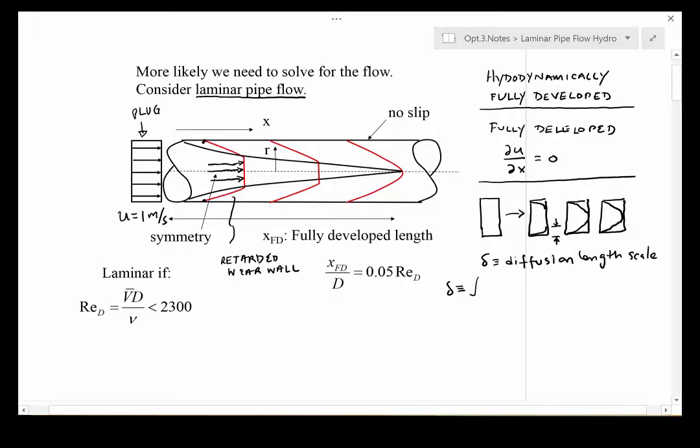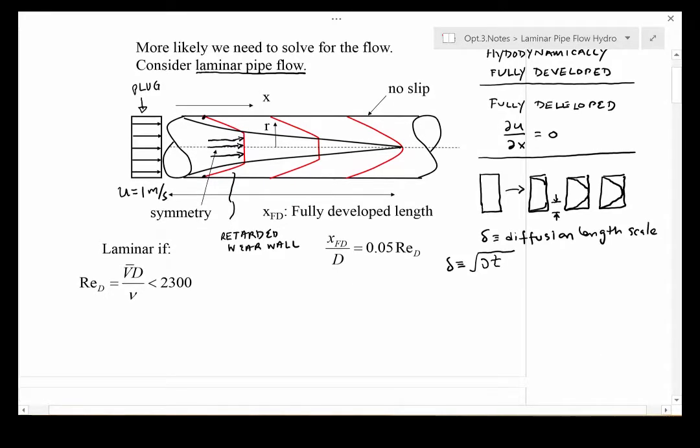There's a very similar relationship in the momentum problem that depends on the kinematic viscosity times the characteristic time. So for the momentum problem, the parameter of importance, nu, is the kinematic viscosity, with units of meters squared per second. This is what affects the molecular process of diffusion into the system.